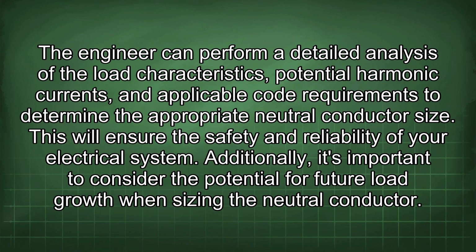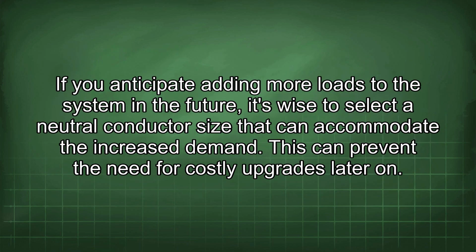Additionally, it's important to consider the potential for future load growth when sizing the neutral conductor. If you anticipate adding more loads to the system in the future, it's wise to select a neutral conductor size that can accommodate the increased demand. This can prevent the need for costly upgrades later on.